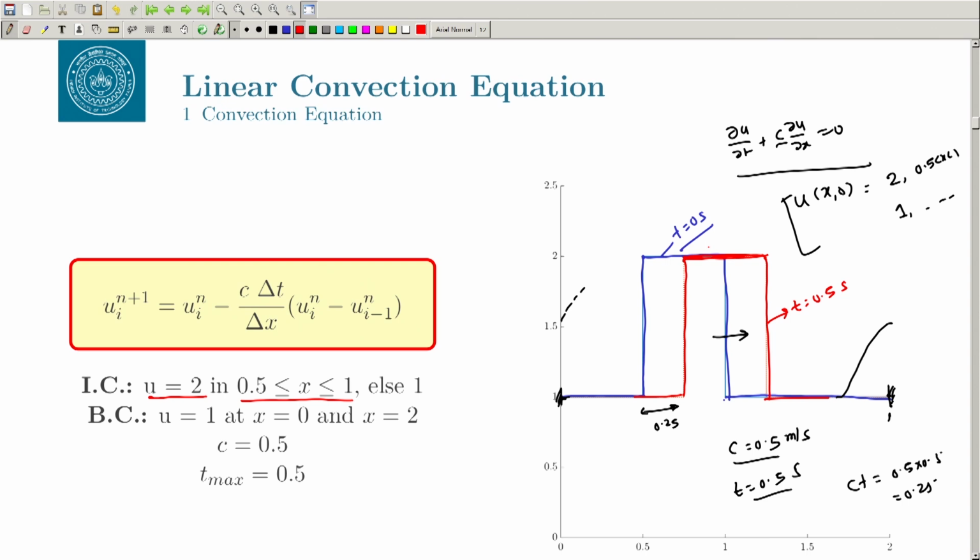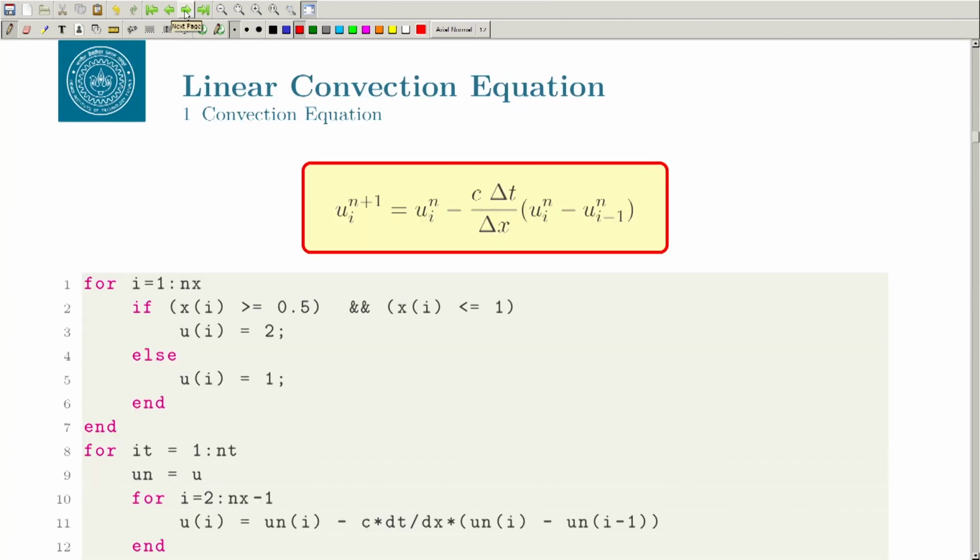So, I have shown you the initial condition and the final condition. Let us see what the intermediate conditions are and what schemes and parameters you are using for the solution. So, you can actually go back and quickly write a simple MATLAB code. For example, what you see here is my initial condition, we have defined our wave, and this is the same expression, a pseudo code for solving this equation. This is u_i^n, c delta t by delta x, and dt and dx you can fix.